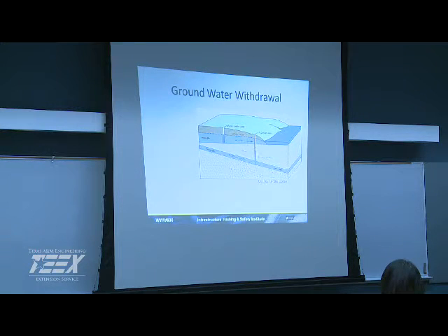This is what we were talking about earlier, when we look at a combined aquifer versus a shallow water table aquifer. Again, in a water table, the actual level, if you went out and measured, if you had a well casing you wanted to stick a transducer down into, you can actually see the water levels change. In an artesian aquifer, it's under pressure, and they'll actually blow up out of the ground depending on where you drill it.